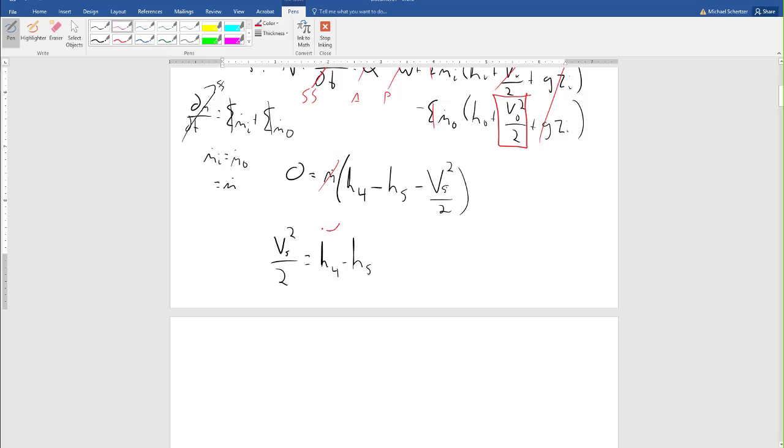But if I think about the units here, anytime the kinetic energy term sticks around, the hair on the back of my neck stands up. The enthalpy is in kilojoules per kilogram, but here right now this is meters squared per second squared, which is meters times meters per second squared.